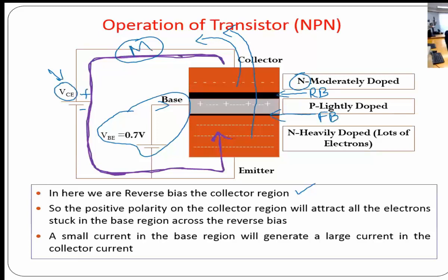So yes, it can be visualized like that. Definitely two PN junctions, because a PN junction is nothing but a diode, correct? Which source are we talking about? The requirement for NPN: if you want to turn the transistor on for NPN, the base should get more than 0.7, or at least 0.7.